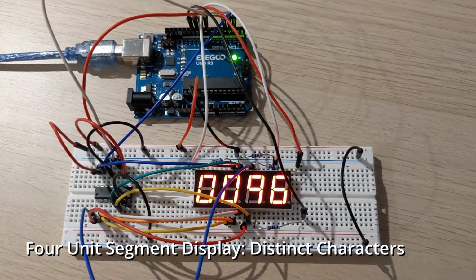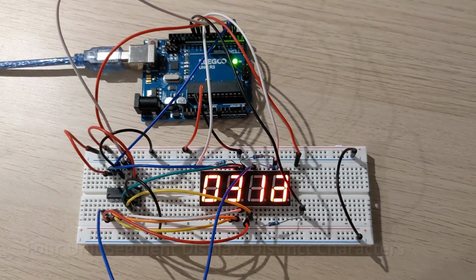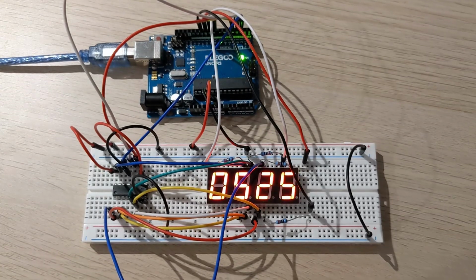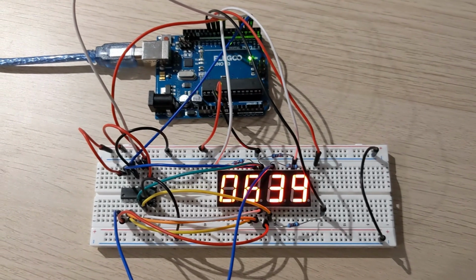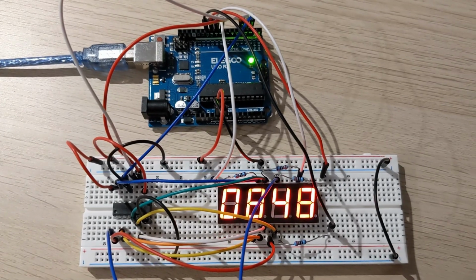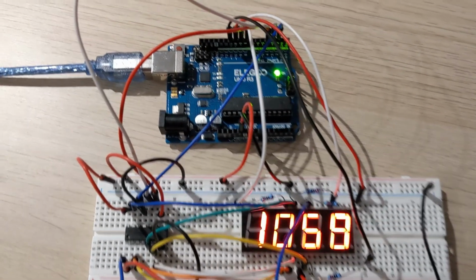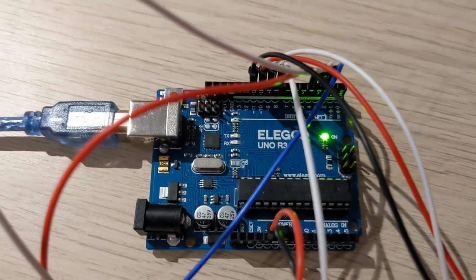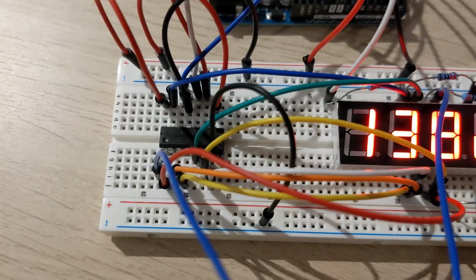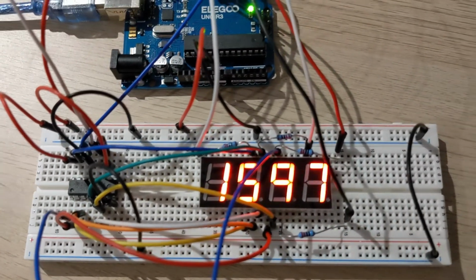So, in order for each of the units to present their specific segment pattern, we need to write the pattern and then select which of the units should have this pattern written to. Wait for a short amount of time, and then move to the next unit, where we'll do the exact same thing. Only this time, selecting the unit or units that should have this pattern written to. And here, I'm doing exactly that, and made each of the units represent a digit from an ever-increasing counter.